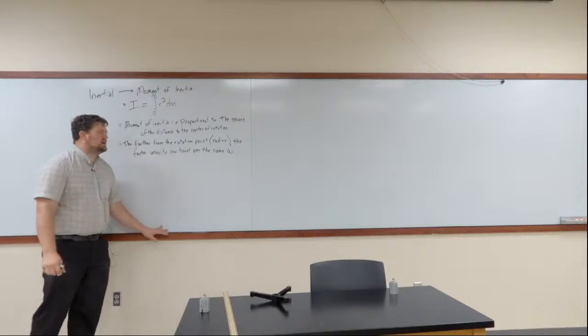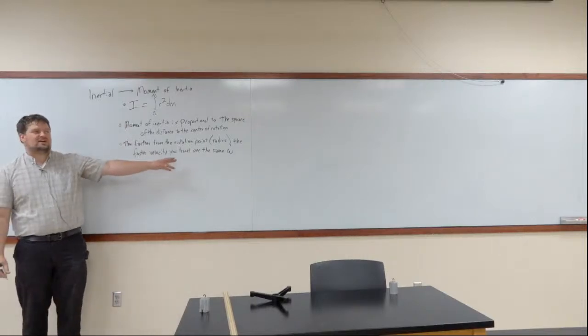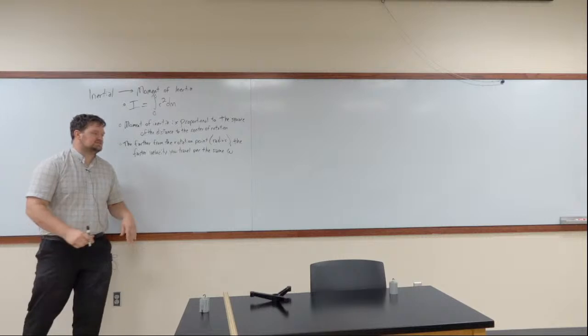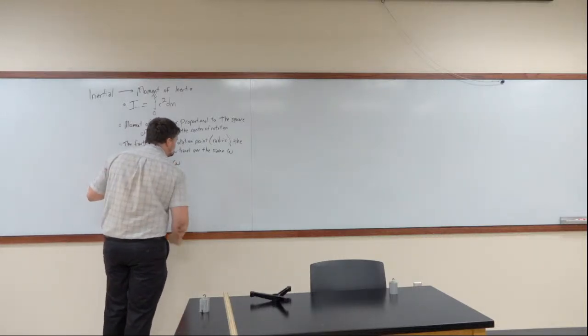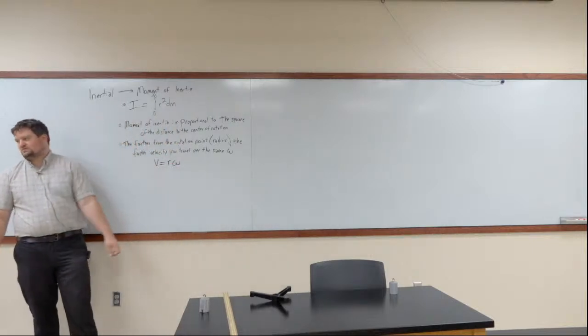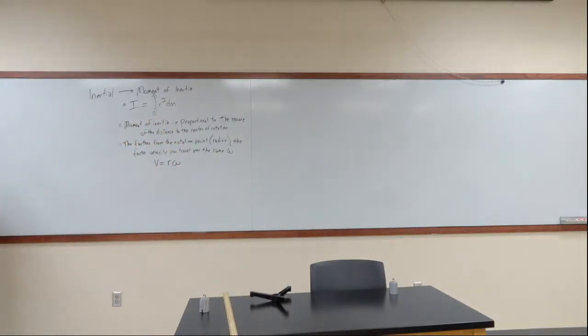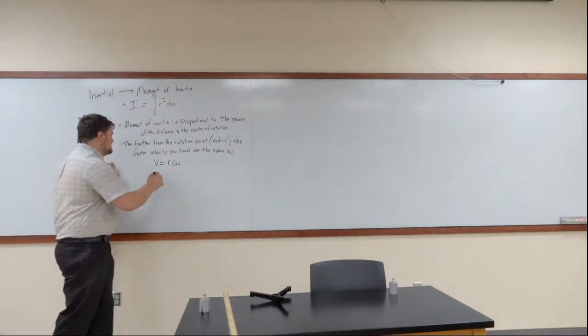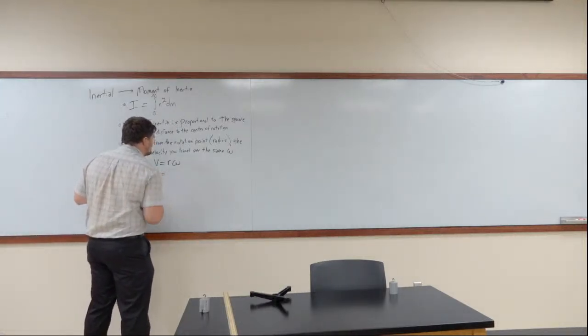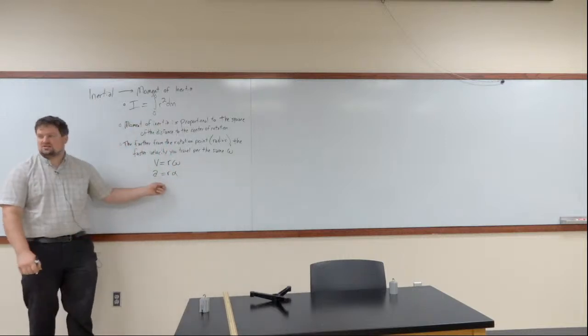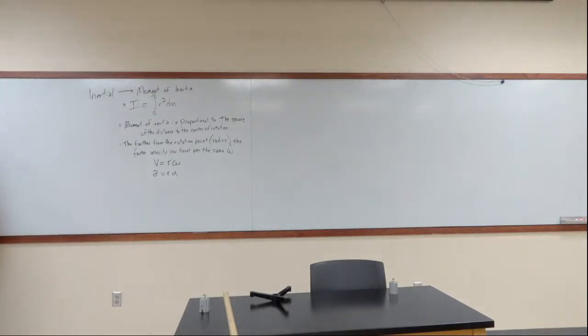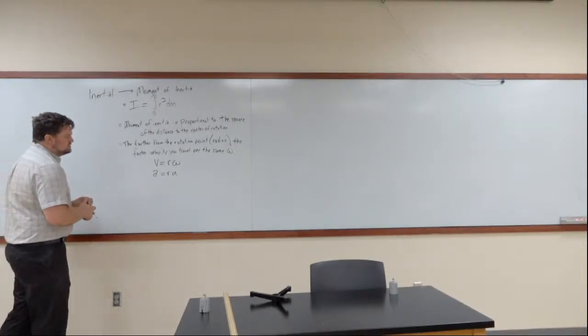So for the same angular velocity, you travel at a faster speed when you're at a higher radius. And the whole reason for that is because we have the relationship V is equal to R times omega. Now, if we were to integrate this, what you get is roughly that your acceleration is equal to R times alpha. That acceleration is centripetal acceleration. It doesn't account for tangential acceleration, which I think you guys talked about a little bit in dynamics class. At least you should have.